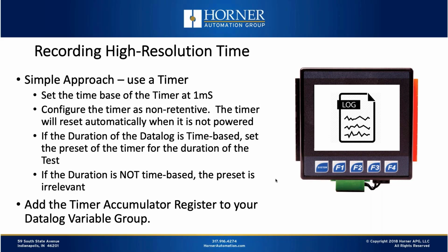We'll configure that timer as non-retentive. That means that the timer will reset to 0 when it doesn't have power. That'll make it really nice for having the timer active while we are running the test. We could also set it up for a longer test. We could also set it up so that that timer expires automatically every second and restarts every second, so that we effectively have a millisecond range that we can look at, but we won't be doing that in this example I'll be showing you.